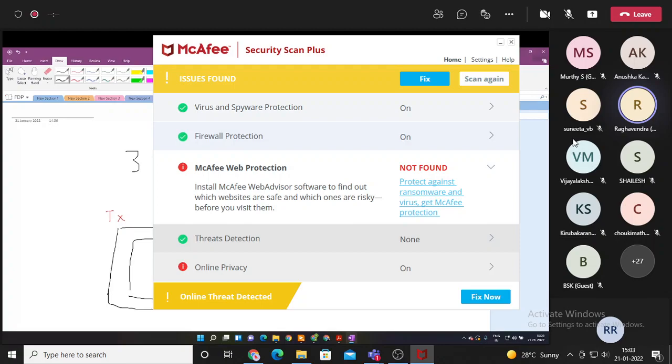So you have a port here, you have a port here, I, Q. We will only be using one, either I or the Q. In VLC, we do not need both I and Q. We will only be using one of them. So the second USRP will have this receive port, and our signal will be coming in either through one through this and one through this. Now, this is the change that we've done in the USRP hardware.